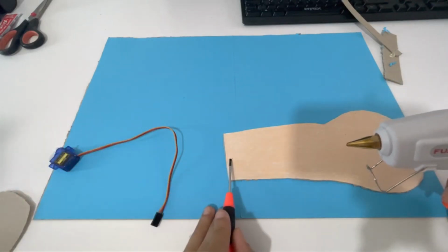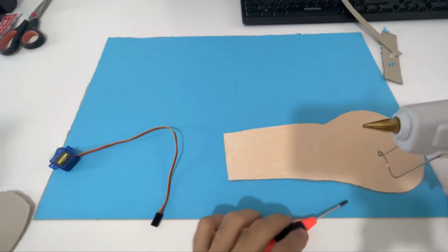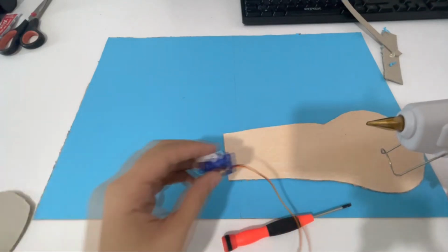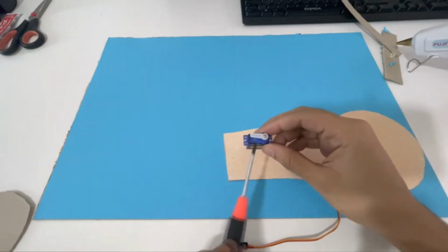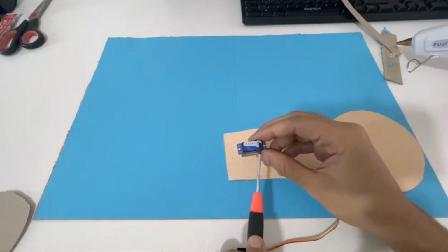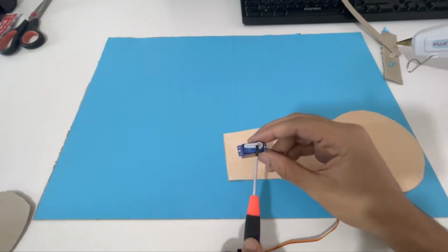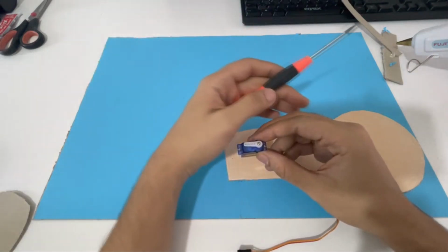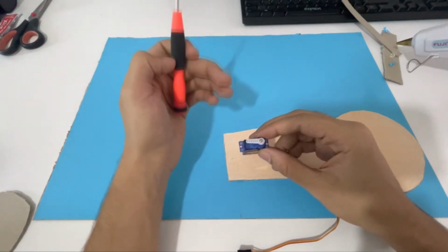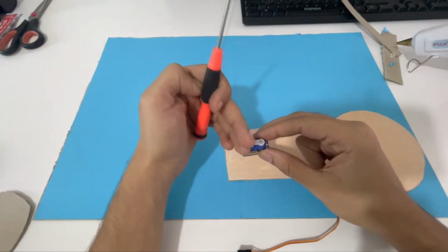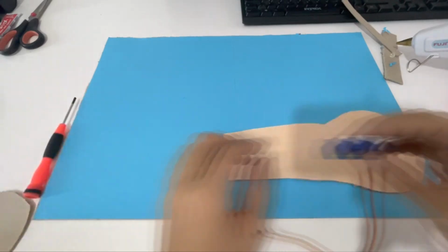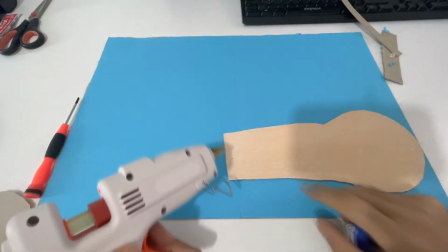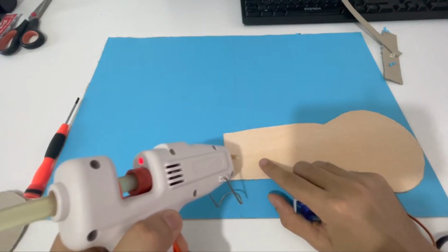As you can see, the midpoint of our elbow is defined by the blue line. Also, I would like to inform you about this issue. It's important that we position our servo motor, because we will control our servo motor between 180 and 90 degree. For this reason, we must position like this, as you can see here. So let's continue. First of all, let's squeeze our hot silicone to the middle point. Then let's keep our servo motor on it.